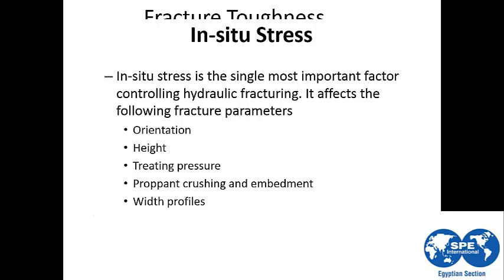In-situ stress is the single most important factor controlling the hydraulic fracturing itself. The formation in-situ stress is the total stress applied on a single point or single sample from the reservoir rock. It controls the orientation of the frac, height of the frac, treatment pressure, the proppant crushing and embedment, and the width and profile of the frac itself.